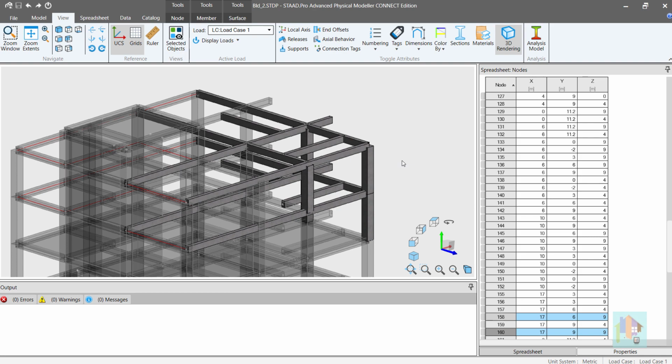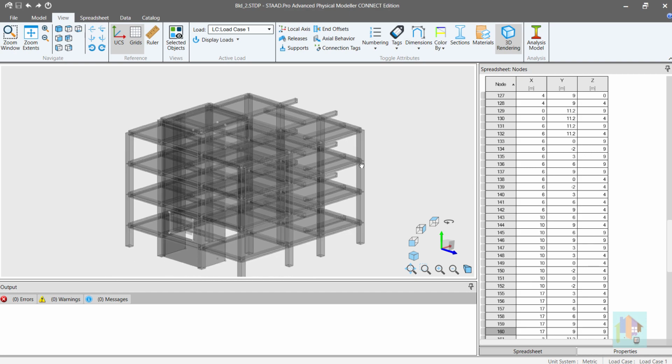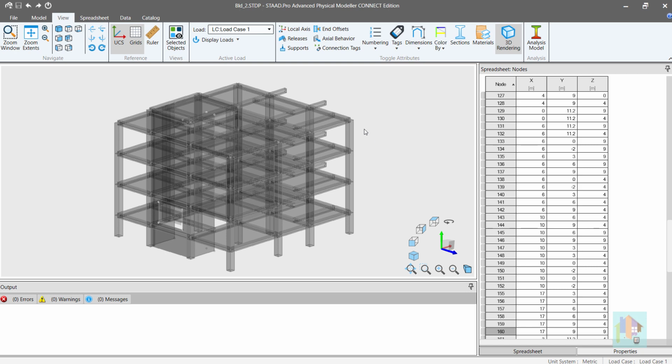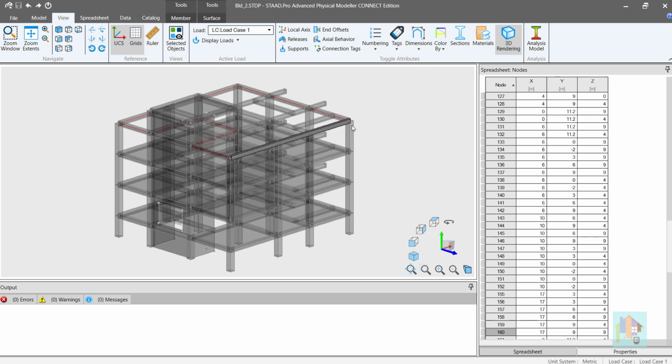For example, consider a gusset plate brace member connection where the bracing member doesn't span till the beam junction and ends in the gusset plate. So in such case, you need to assign offset value. For concrete member, it is often required to match the beam column alignment such that they are top level plus. In analytical modeler, you have to calculate the offset distance and direction manually and then assign this to the member. For thousands of members with different offset value, it is very time consuming.